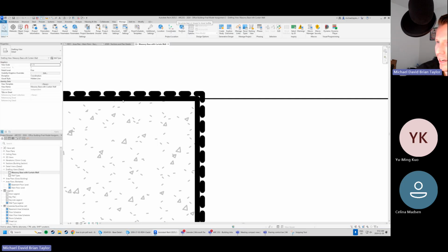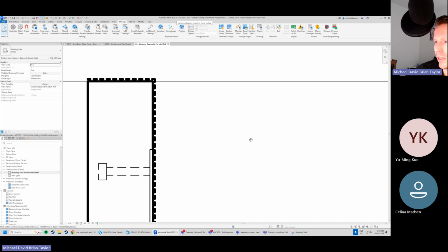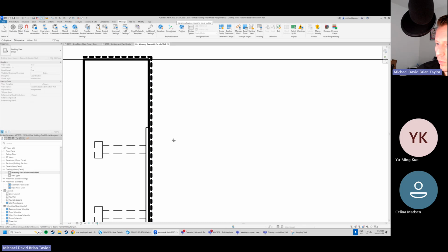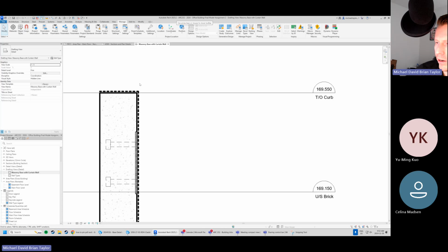And that's okay. So I've gotten in trouble for this before, but I'm going to show you something that I like to do. This is all up to personal drawing preference and the drawing standards of whichever firm you happen to be working for. I can see here that I might want to offset by 1 millimeter or so. So I'm actually going to offset this by 1 and turn off copy and just give myself a little bit of space off of the element here, right?